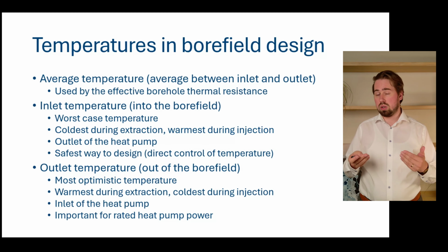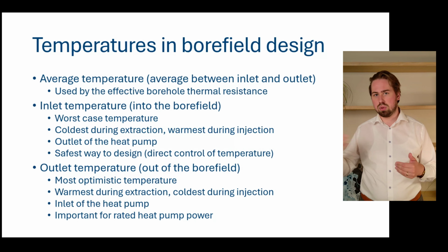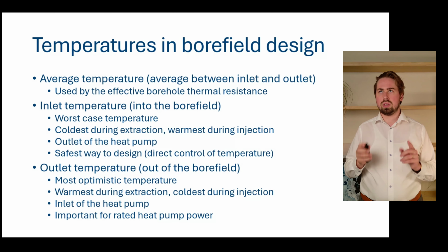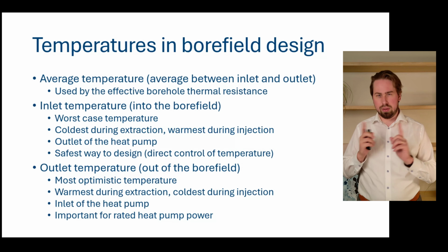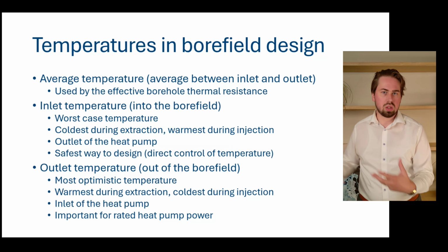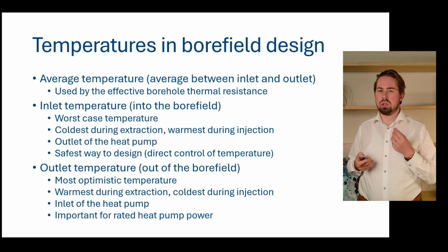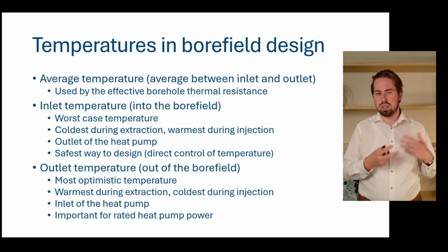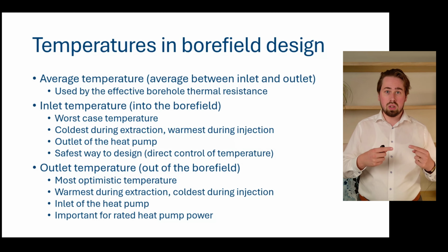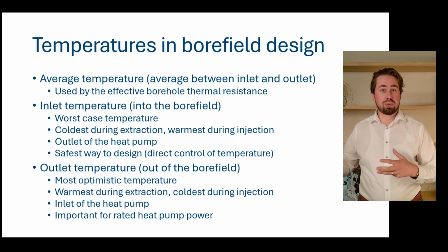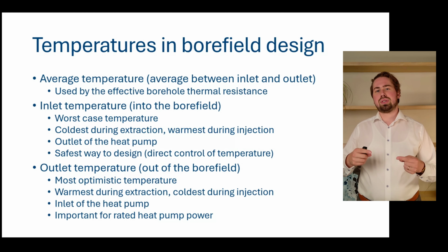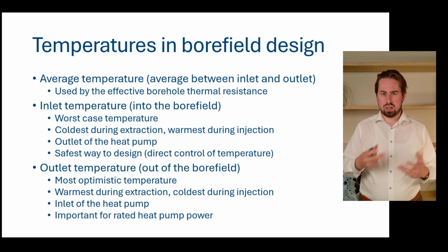And also when we go to the next chapters and talk about required borefield size and borefield depth, it's important to think: am I caring about the average temperature and the traditional way of designing systems, or do I actually want to reason with the inlet or the outlet temperature? Because that will change the required borefield size, because the temperatures are, as said here, either an average or the best or the worst case.